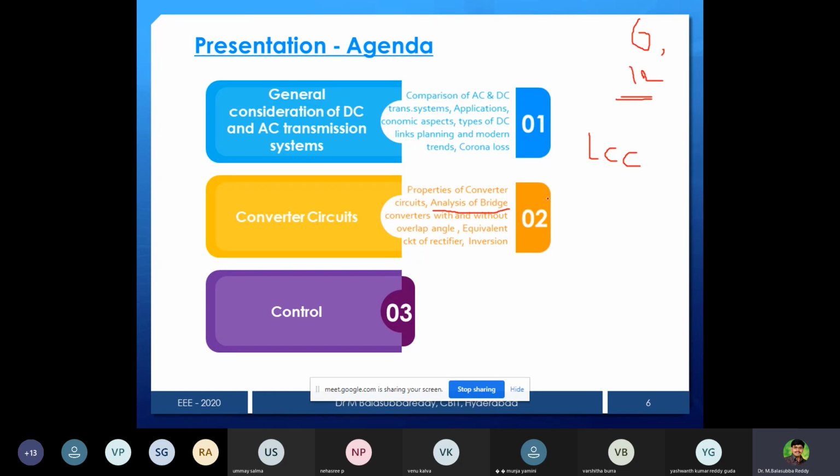And in HVDC converters, there are multipulse converters also. By multipulse, we mean that obviously 6 and 12 pulse converters are used. And we use the LCC converter for all the controllers, rectifier station or inverter station, because the supply on the source side is an AC supply, which we make use of to commutate the device. This is a very sensitive parameter in high power application, when a valve misfire may take place, or the device has to be properly turned off.